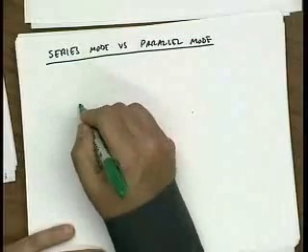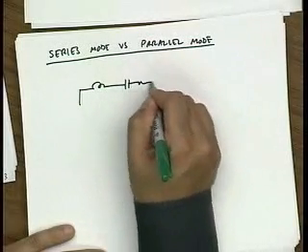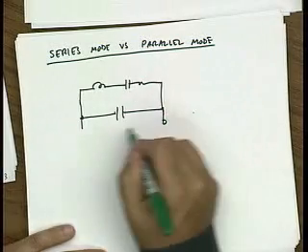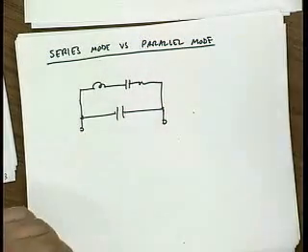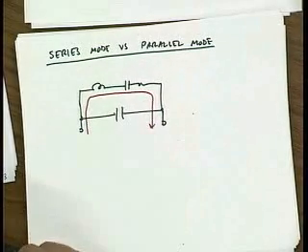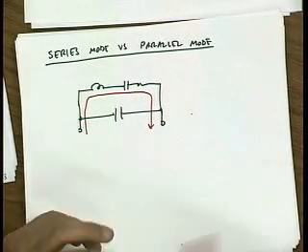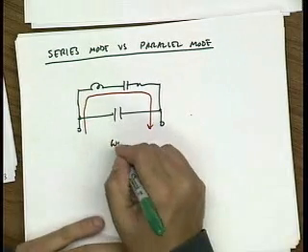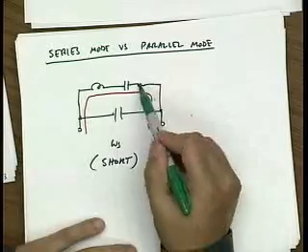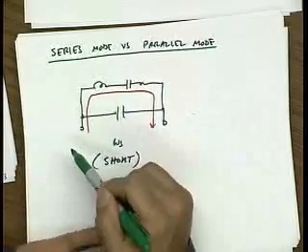Okay, so the series mode, if I think of this simple model for the circuit, would correspond to, let's say, resonance occurring through here. So omega s, which we call the series resonant frequency, has a very small impedance. If this is very small, it looks like a short circuit, right?